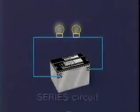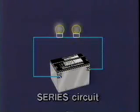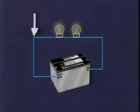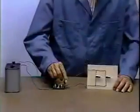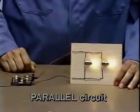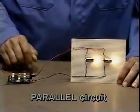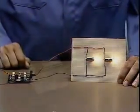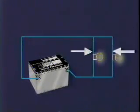If we add another load to the circuit, then we have a series circuit. A series circuit may include more than one component, a switch, a lamp, a motor, and so on. A series circuit is formed when all the current flowing through one component also flows through another. Thus, a series circuit will have one and only one path for current flow. A parallel circuit is formed when the different loads are arranged in such a manner that current can flow through one component without first having to flow through another component. A parallel circuit is therefore defined as a circuit providing two or more paths for the current flow.